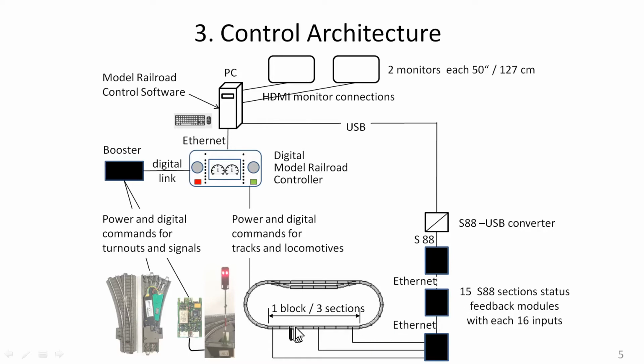If the train then comes to the middle section, again it sends a signal to the controller software, and finally at the last section. So for example, the controller software has command points that in a first section the locomotive gets a command to ramp down the speed to stop neatly in front of the red signal at the end of the third section.